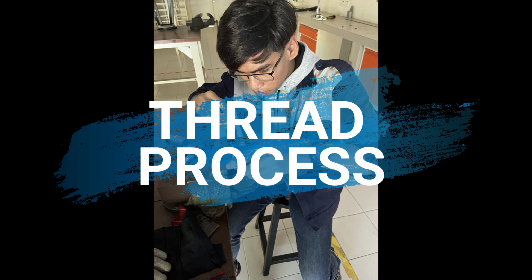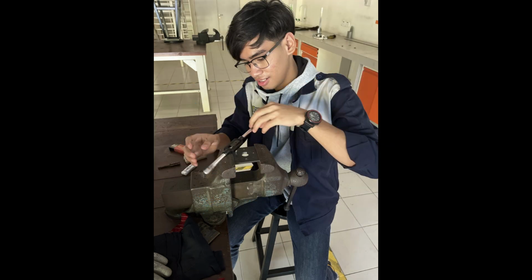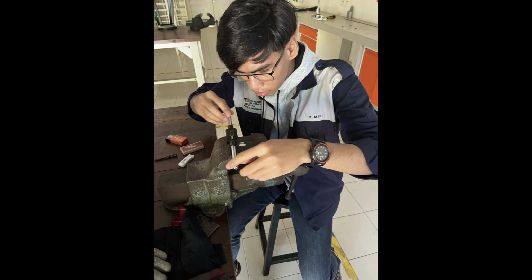After milling, we proceed to tapping. To thread the steel plates, we used an M4 threading bit. We mount the first threading bit on the hand tap wrench. Then we spray the holes on the steel plates with WD-40 to give a smooth tapping. Then we thread the holes slowly and carefully to avoid breaking the thread bit. After that, we proceed with tapping using the second and third threading bits with the same process.